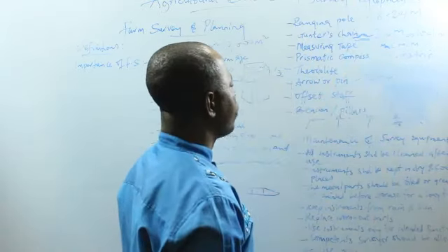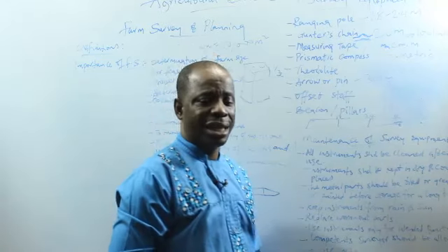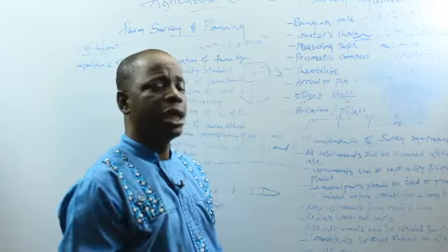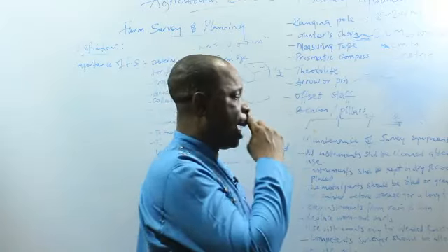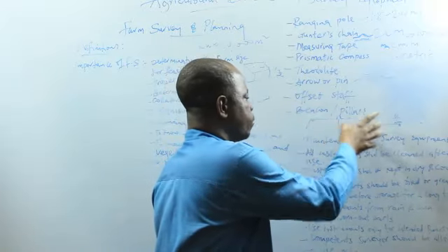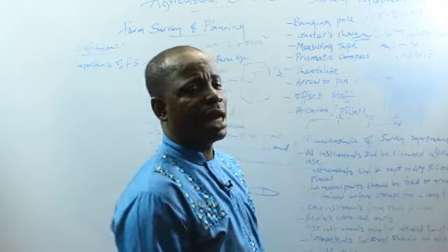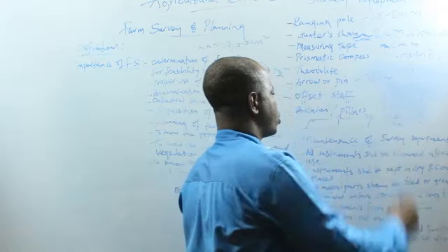Now, this offset staff is like a yardstick that's used by the people selling clothes in the market. It is 36 inches long and it is marked in inches and in foot. So it has 3 stages: 12, 24, 36. One end of it is attached to a ring.